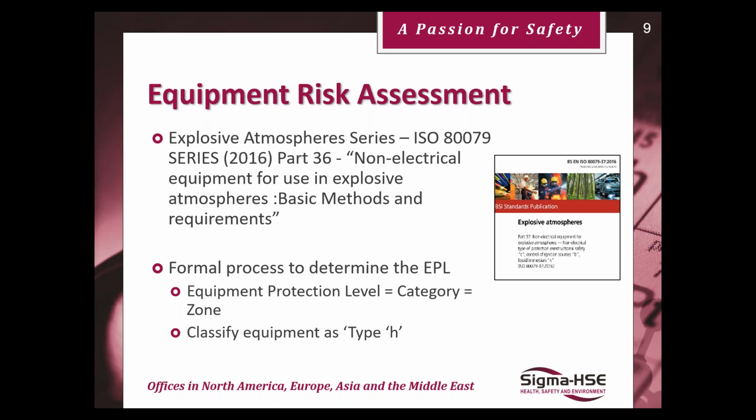Typically, if a flammable atmosphere is occurring continuously, it will be a zone 0 if it's vapors, or zone 20 for dusts. Now, if it happens as part of normal operations, just intermittently for a short time, then it's usually a zone 1 for vapors, or zone 21 for dusts. This is typically something that's being poured as part of normal operation, like filling the manway of a reactor for a short period of time, where you create it intentionally. That's a zone 21 or a 1, depending on the materials used.